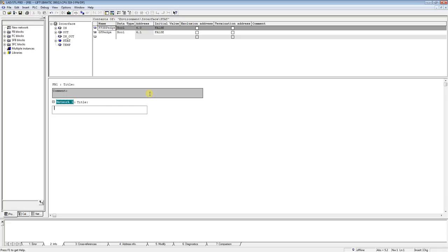We have to control a motor, and let's see a condition for control of the motor. I have to get a feedback from the ground floor conveyor to start my lift, and I need to have the platform of the lift at sensor ground floor. So this is a condition for these 2 sensors. For sensor and for feedback, it is ground floor feedback and ground floor sensor.